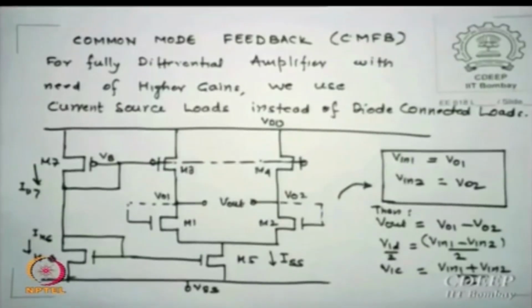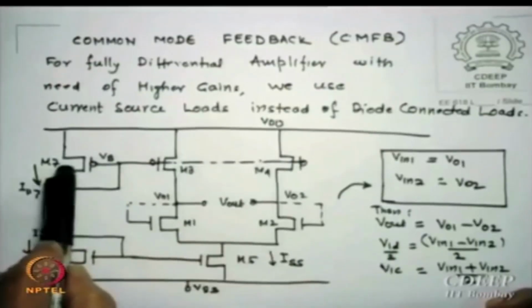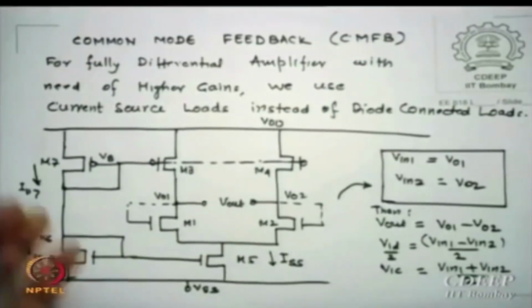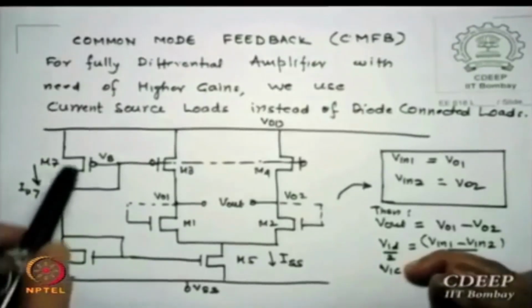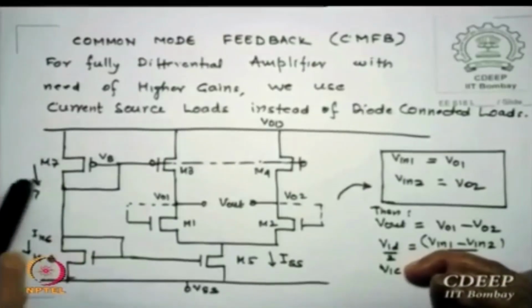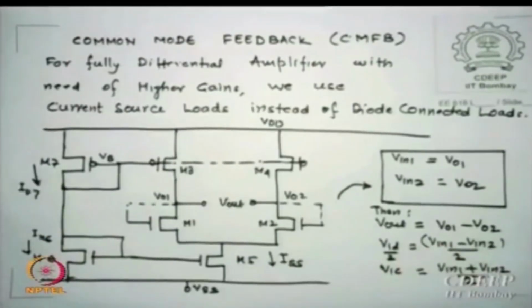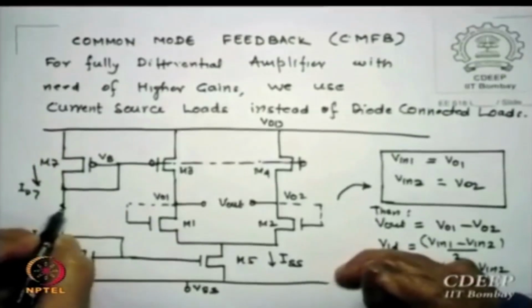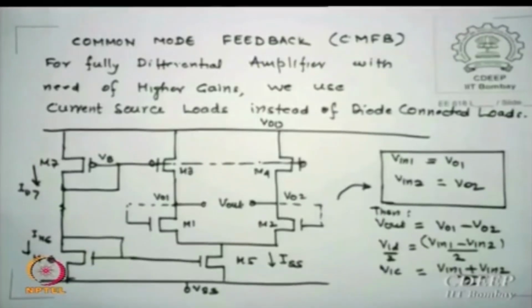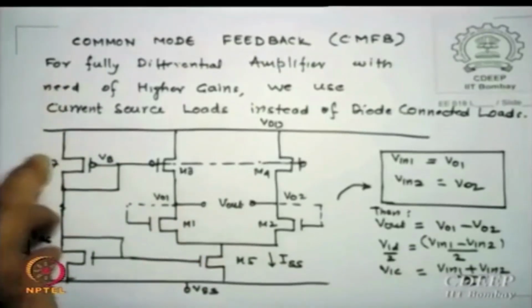My problem is now something more. My assumption is that this current ISS is governed by this device, and this potential is governed by this P channel device, which is also a current source. Let us say, for a variety of reasons, sizes, variabilities, whatever, these two currents are not equal. Kirchhoff's law forces the currents to be equal, but to put it non-equivalently, I put a small resistor in between which can then control the current, and drops here or not here.